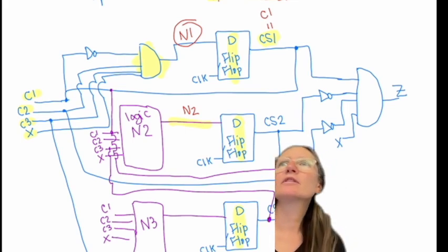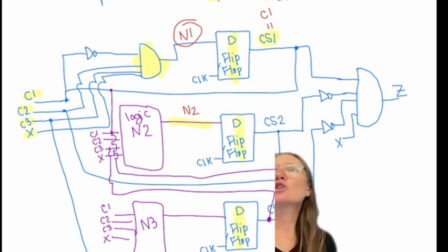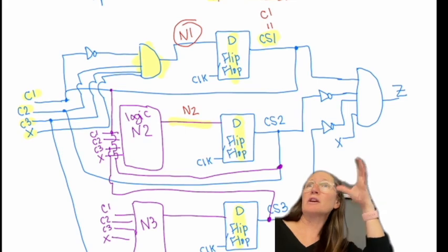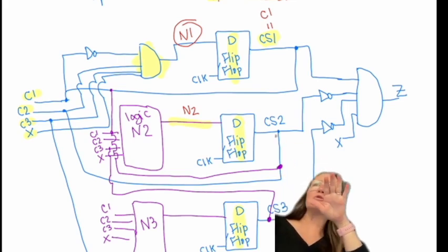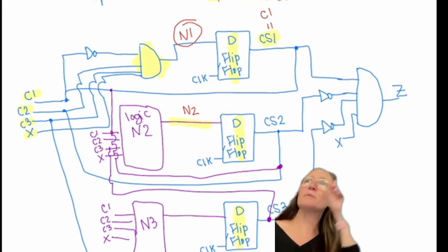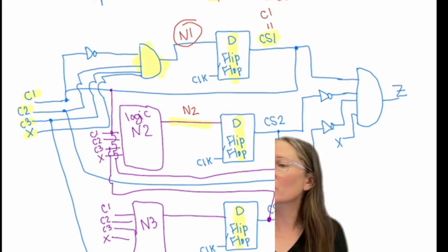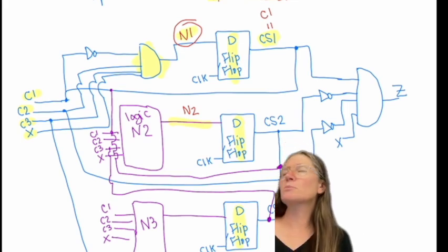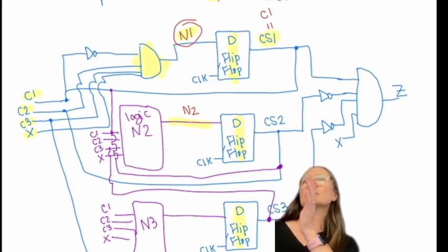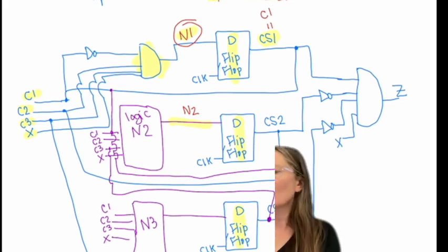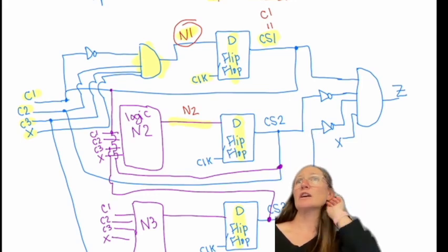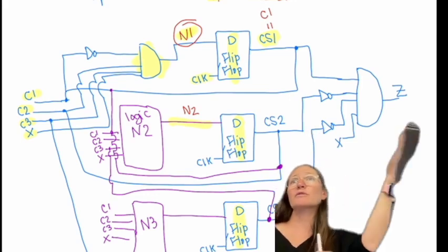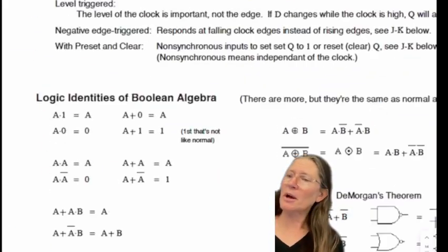Yeah. What's the purpose of the feedbacks? So that flip-flop is like a memory, and so it's keeping that number in there. So that when you clock it, it's going to change based on the input. So here, my next input then becomes my current state. So with the clock, that input becomes the current state. And so as I move through each of those states, back to this one.